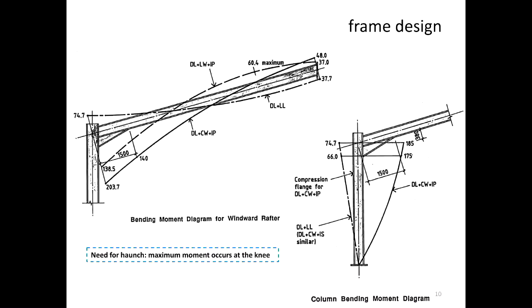So what will happen, they will just remove the flange of that hunch and weld that web to the flange of the standard section. So that's how the hunch is formed. Sometimes, and I think I mentioned that yesterday, I will just draw that so that you see what it looks like. Sometimes you can have a much deeper section used for the hunch.